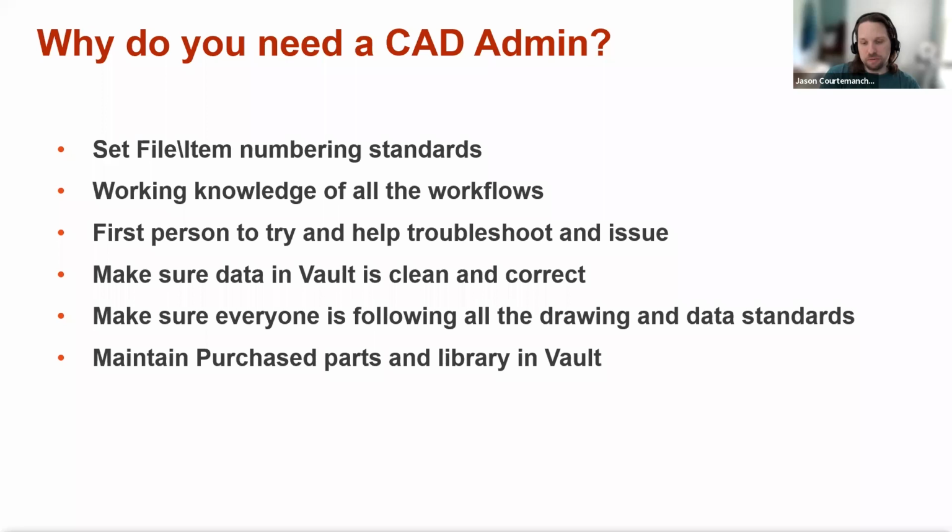And like you mentioned, it all goes back to clean data. If you're just starting, whether you have Vault or not, as far as I'm concerned, it's the file naming from day one. It takes a lot of time to go back and rename things, and in Vault, the file names create the items that eventually get linked to PLM or ERP. Cleaning up that data so that you can link those to other tools can be a big lift. So it's good to think about that in the beginning, making sure that the file's right, that you have the right metadata so you can actually easily find and reuse.